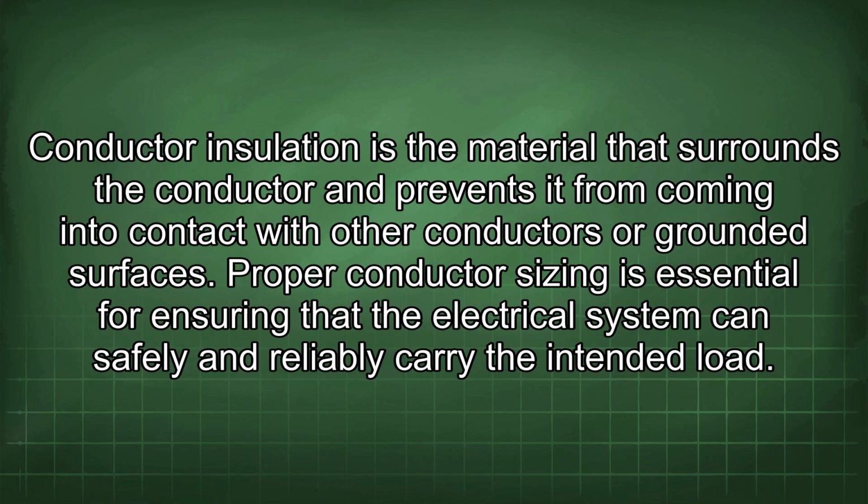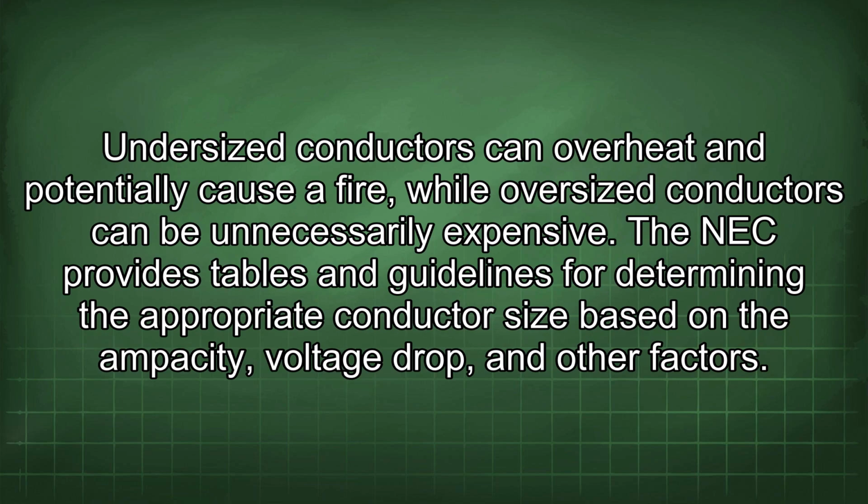Proper conductor sizing is essential for ensuring that the electrical system can safely and reliably carry the intended load. Undersized conductors can overheat and potentially cause a fire, while oversized conductors can be unnecessarily expensive. The NEC provides tables and guidelines for determining the appropriate conductor size based on the ampacity, voltage drop, and other factors.